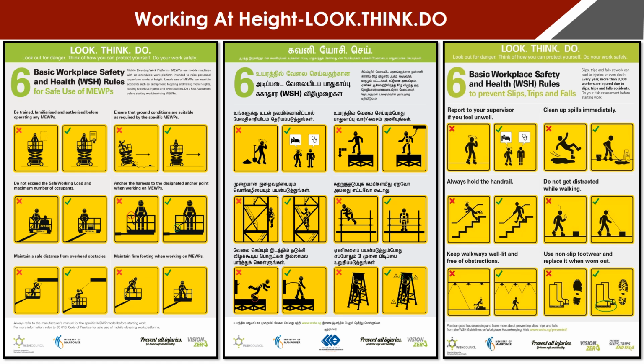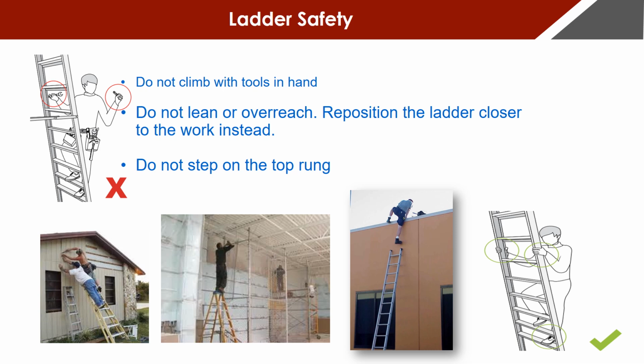From the Ministry of Manpower, MOM, Workplace Safety and Health, WSH, Council Dos and Don'ts. Ladder safety: do not climb the ladder with tools in hand, do not lean or overreach, reposition the ladder closer to the work area, do not step on the top rung, use the buddy system where required, do not place ladders near openings, walls, or walkways.